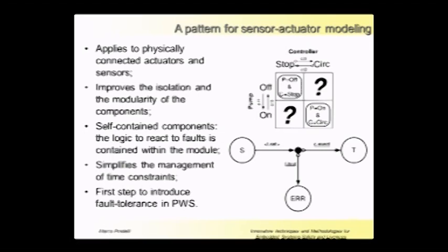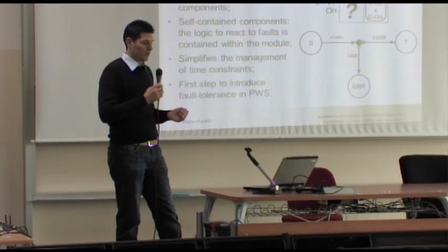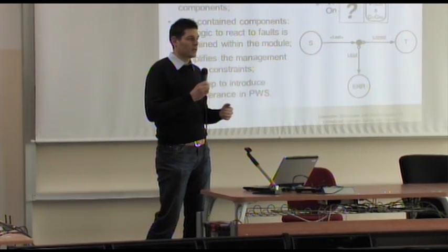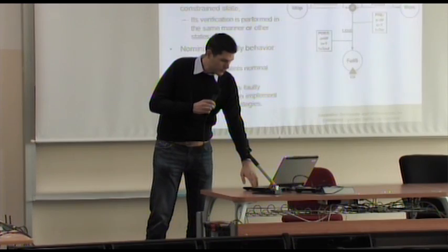For this reason, often a sensor is attached to critical actuators in order to provide feedback to the system related to its operativity or its failures. So we can introduce a wait state in which, after having sent a command and set a timer, we wait for a positive event coming from the sensor or a timeout. That means that our command has not been executed.